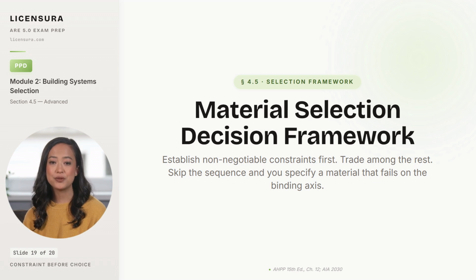Every architect on a first major project has tried to select materials by aesthetic preference first and then backfill the technical requirements. That sequence fails, and you'll redesign in design development when the code official rejects the material's fire rating or the structural engineer rejects the spans.